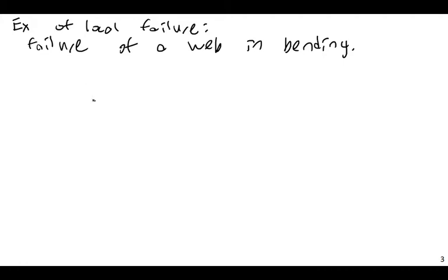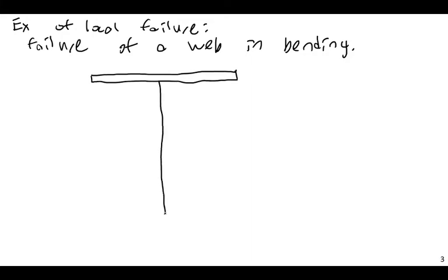So for example, imagine I build up a section out of, I don't know, steel plate, just regular old steel plate. And I go ahead and give it just massive, massive proportions, but with a deliberately incredibly skinny web. So this is me basically trying to build a section deliberately with the intention of it failing in some local failure mode.